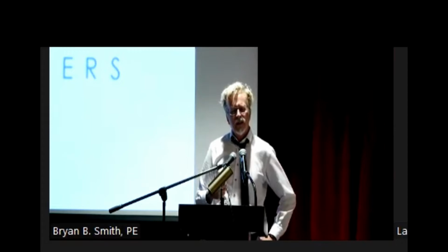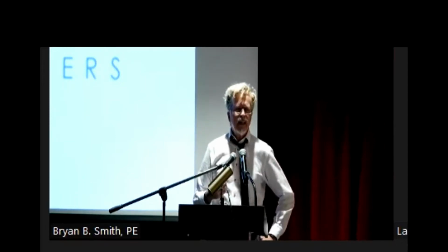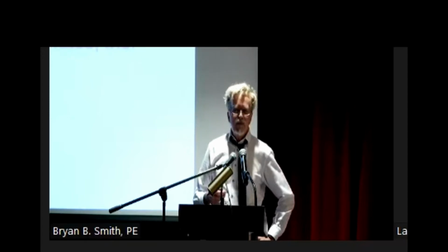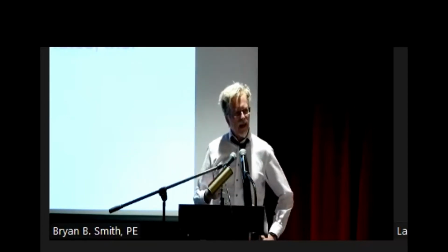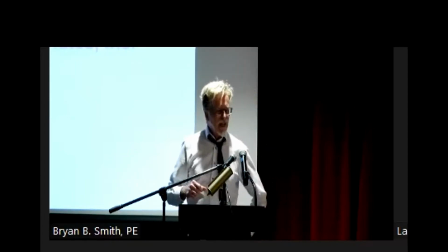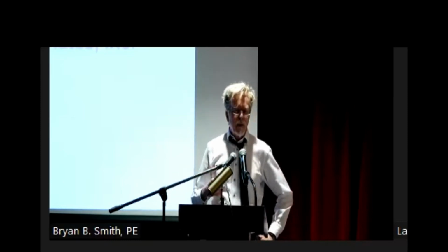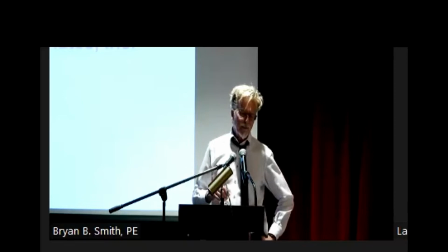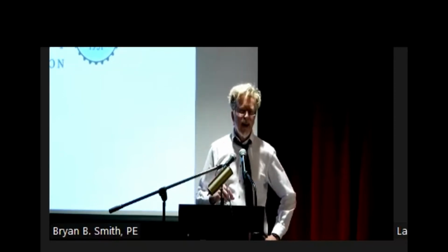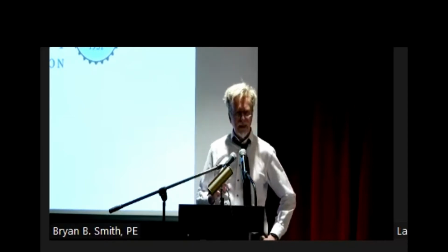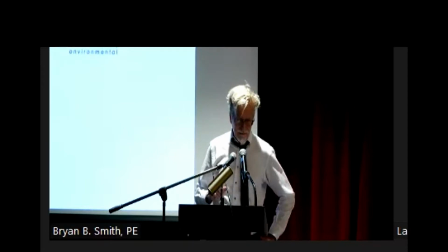Okay. So the idea is that we want our check valve to close before that wave goes out and comes back at 4,000 feet per second. If it doesn't, and I got some examples, I had a pump station in San Francisco, a sewage lift station. I was pumping 10 PSI. The engineer who designed the system and did the surge model, steady state, 10 PSI.